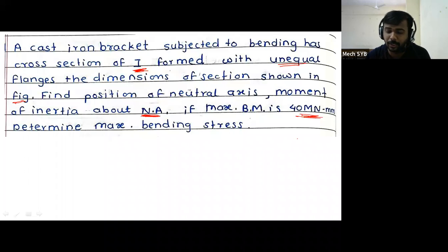Then moment of inertia. We are calculating the moment of inertia about the x axis, meaning we are calculating only Ixx. For any calculation, we are not calculating the Iyy value, because we always assume that the section is symmetrical about the y axis. If it is symmetrical, then the formula will be different. If that section is unsymmetrical, then we have to use another type of formula. But in both symmetrical and unsymmetrical sections, we have to calculate the Ixx value, and that is called the moment of inertia about the neutral axis.